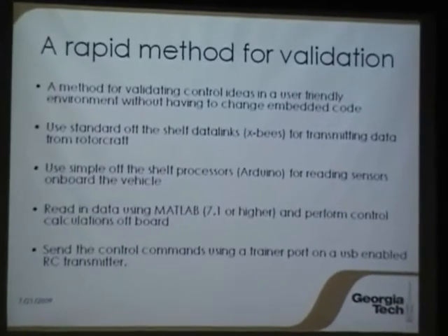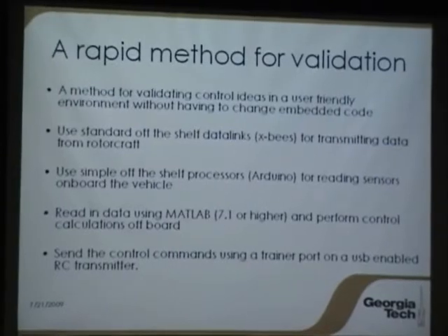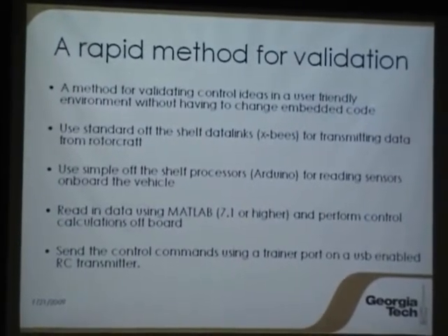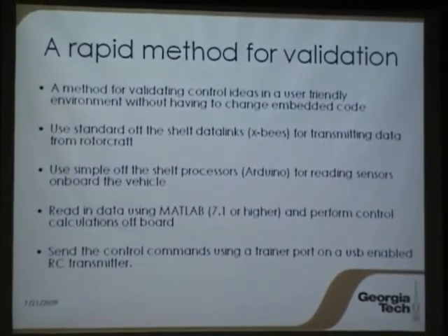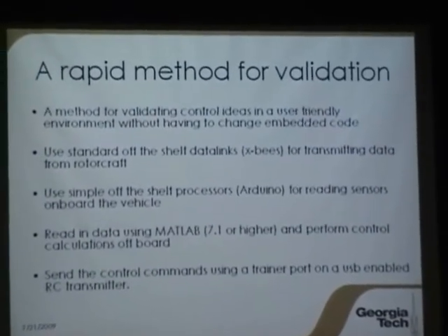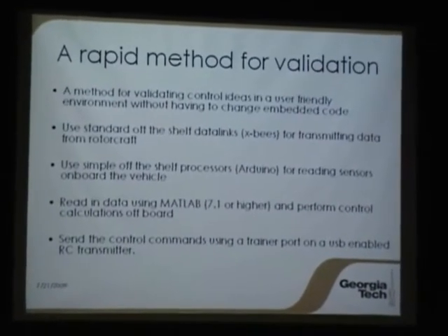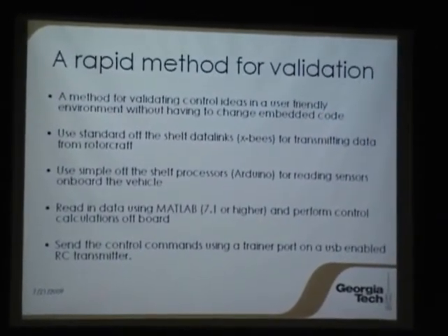The last thing I want to talk about today is a rapid method for validation that we've also used at Georgia Tech for this particular project. This method is based on MATLAB. And I'm not talking about prototyping in Simulink and then converting that code to C. I'm talking about actually having MATLAB code run off-board as the main control logic and communicating with the vehicle using that code.